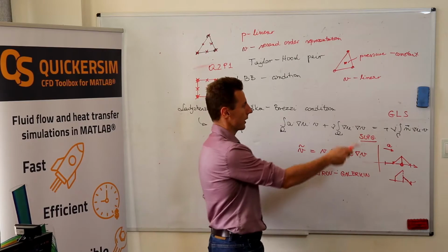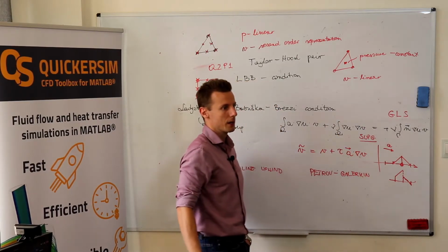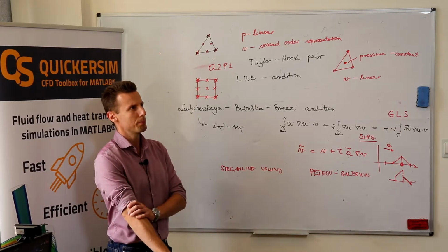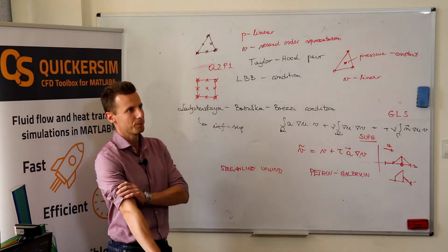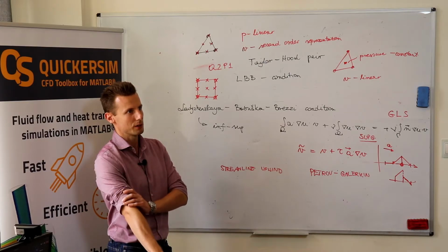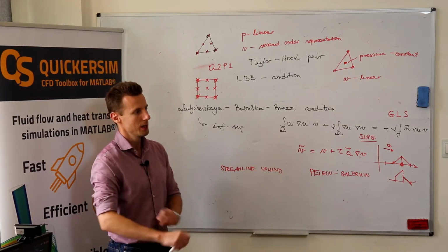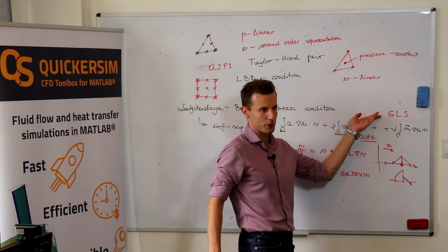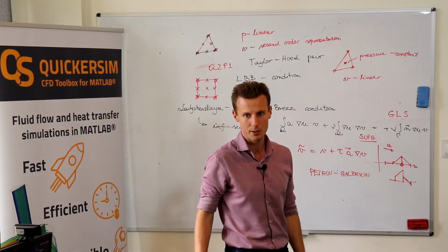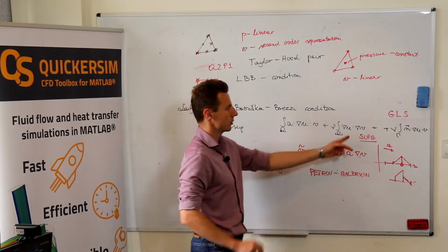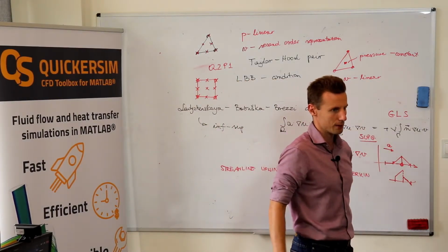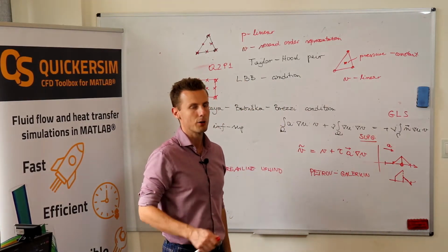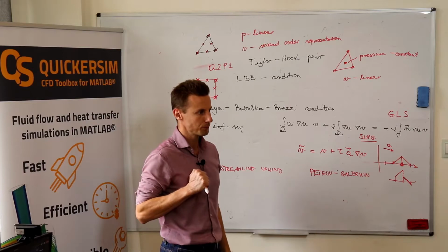You can reformulate this problem with the instabilities, minimizing the square error to minimize the oscillations. Then you come up with the formulation of Galerkin least squares. These are probably the two most popular techniques to stabilize highly convective problems in finite elements.